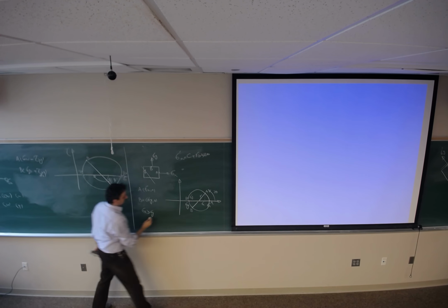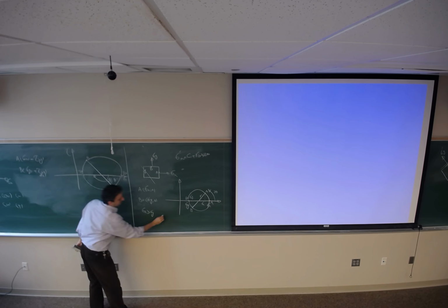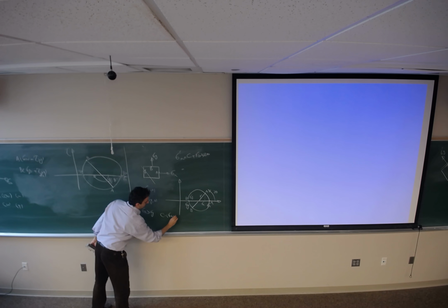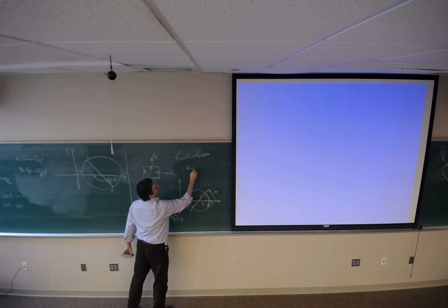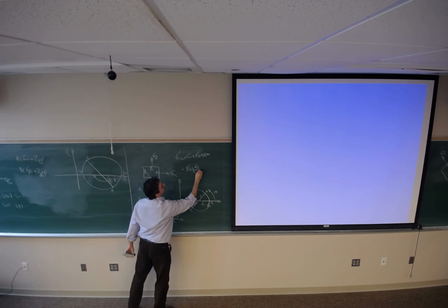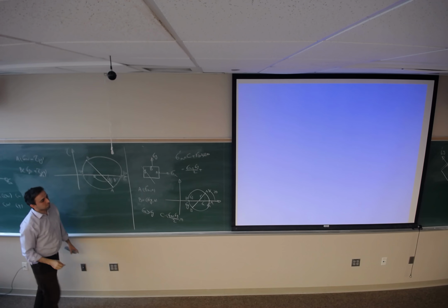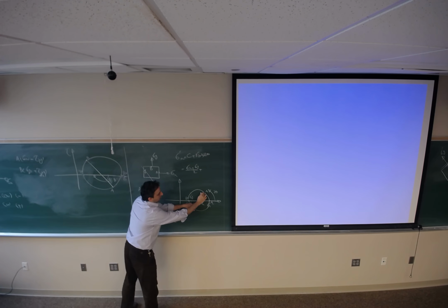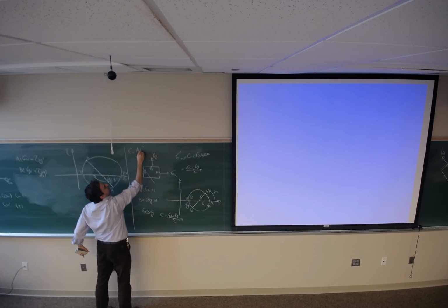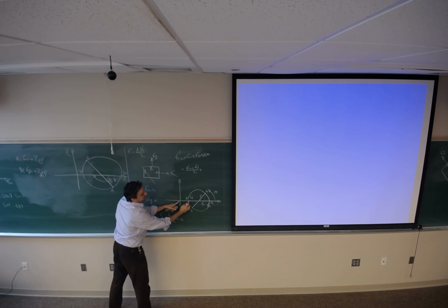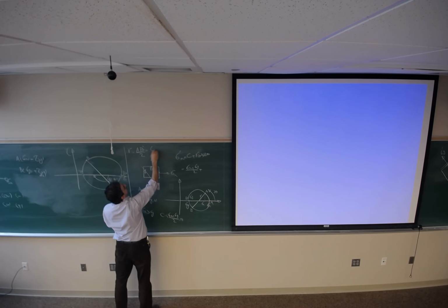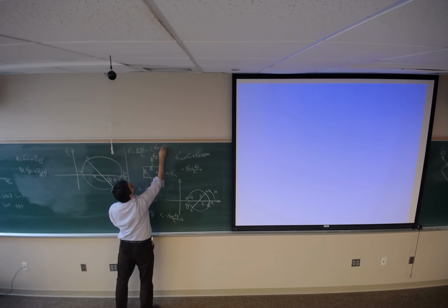What would be the center? Summation of these two: sigma x plus sigma y divided by 2, plus r. R is AB divided by 2, which gives me the radius. And AB is sigma x minus sigma y, so r is sigma x minus sigma y divided by 2.